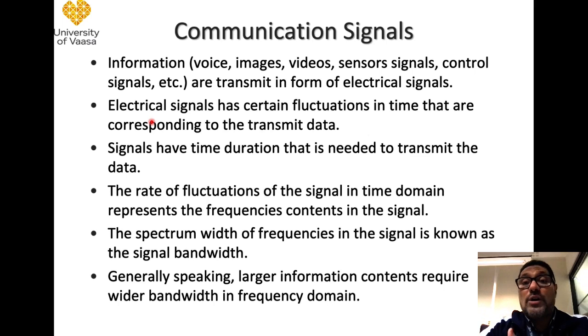For a human voice, usually the signal changes from about 200 hertz, or actually it can be even less, up to about 4 or 5 kilohertz. So this is for the human voice, the minimum requirement for the voice. It is about 4 kilohertz, to have good quality voice. Of course, you can reduce it, but you will reduce the quality of the voice.